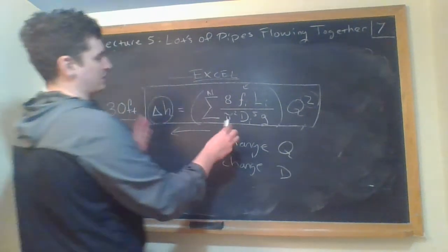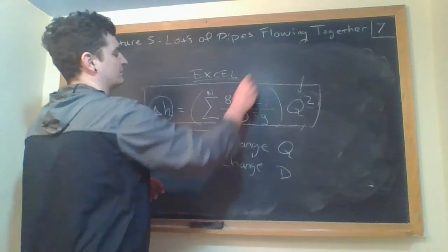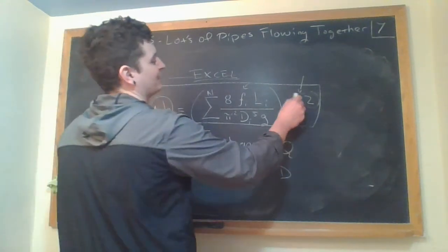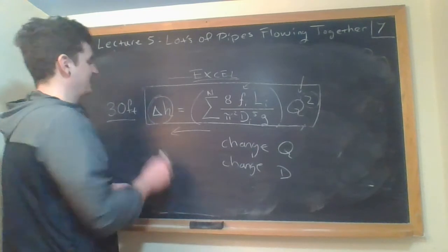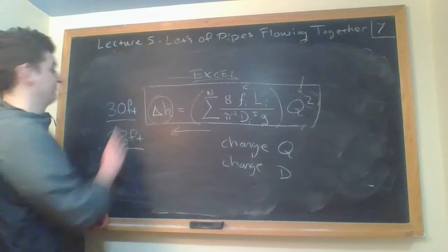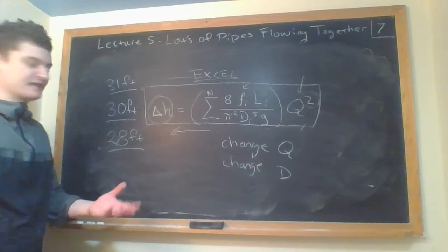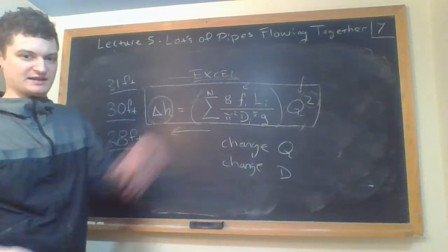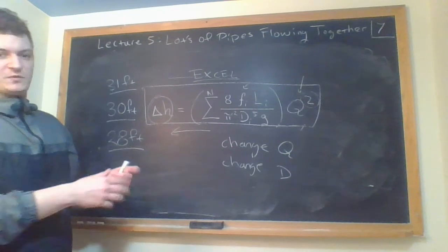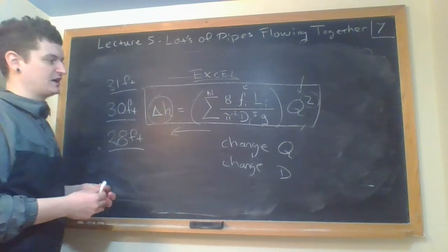And you have your Excel chart that just does this summation out really nice and clean. It references one flow rate, and it does all the work to get the friction factors based on that. And then if I can just figure out the flow rates or some diameter that make it, I don't know, how about 28 feet? How about 31 feet? I mean, how close do I have to be, right? If it's just one guess that gets me super close with my very simple Excel sheet, you won, right? You don't have to do this super MATLAB fancy, get the exact number. This would work just fine.